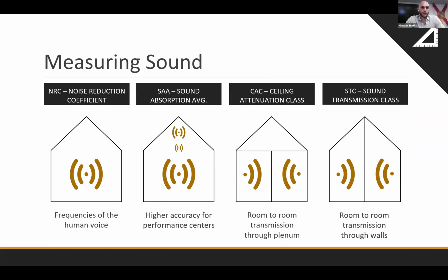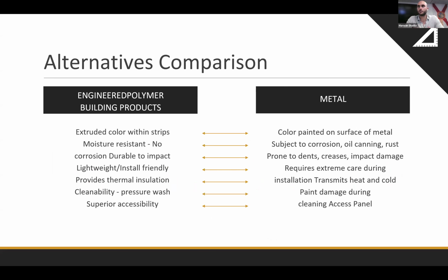I mentioned there's NRC or acoustical properties with the system, and so really straightforward as it relates to Rulon systems. You leave a gap in between some of the panels with some insulation behind it, and noise is able to travel through and be absorbed through that insulation, giving approximately 0.7 NRC value.